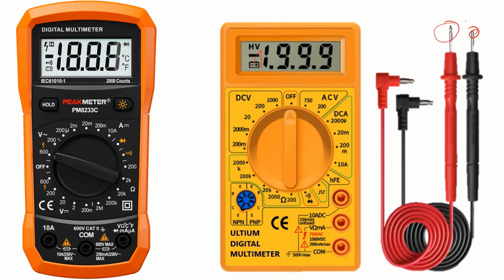When you turn this to any of these regions, it stops being a multimeter and becomes this meter. So that's the ammeter, this is your voltmeter. Now when you turn to the zone of resistance, it becomes your ohm meter. So if you have a resistor and you want to measure the resistance of the resistor using the multimeter, you first of all start by turning this to the resistance zone. Let it become an ohm meter. Then you take one of the terminals and connect on one side, and the other terminal is connected on the other side.